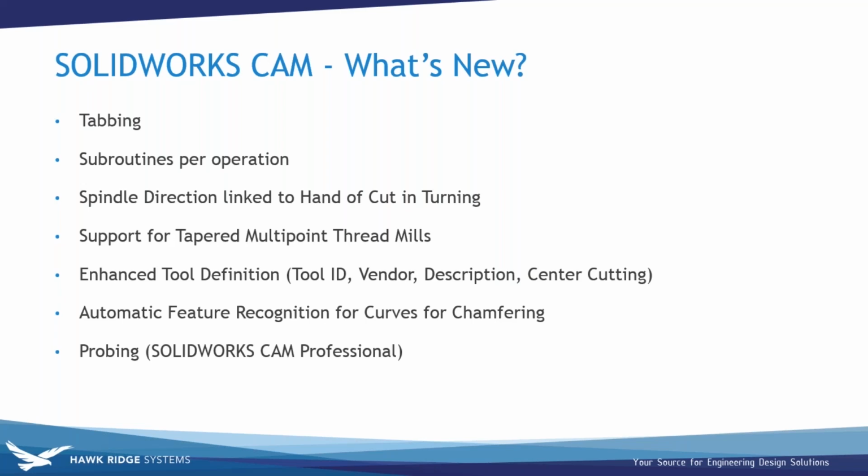Previously, when you looked at an end mill in physical life, you knew if it was either center cutting or non-center cutting. But in CAMWorks and SOLIDWORKS CAM, there was no real differentiation between that. So now we've actually got that capability, and that's going to help you out. It's actually going to flag you with an error message.